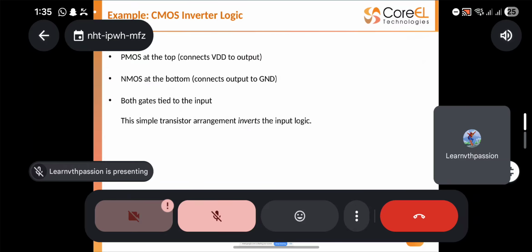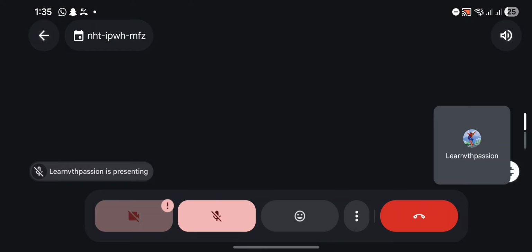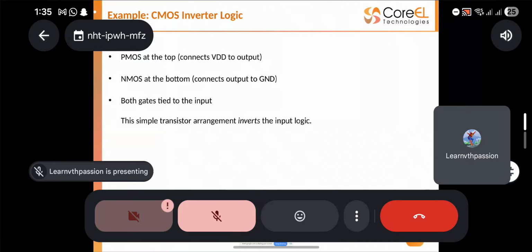So we'll perform the simple transistor level. Here we'll make the connections. For example, if you want to do a NOR gate, you have to see the functionality. To check the functionality, there will be two inputs, VA and VB. So you have to add the V bit. V bit will provide you the sequences, like 1101. You can change the sequences. So you will add V bit for both input A and input B. Once you run the simulation, you'll get a waveform based on the bits you have run, so you can verify your waveform. And inverter functionality, you all will be knowing. Whenever the input is high, the output will be low. Whenever the input is low, the output will be high.